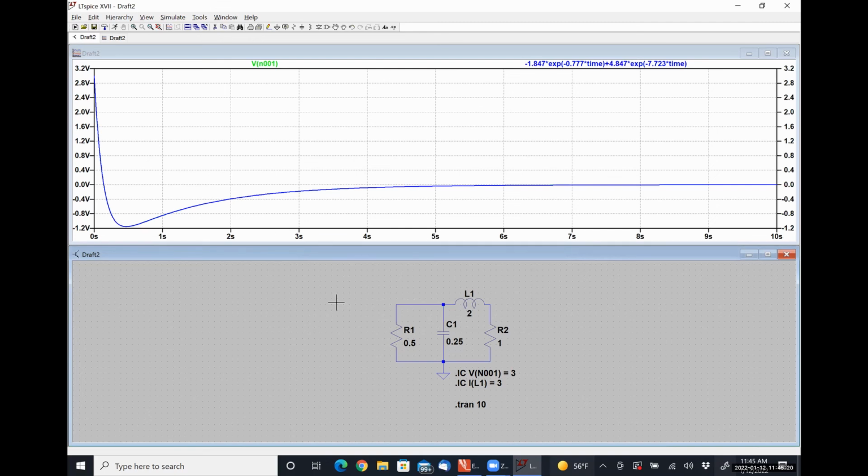And the two graphs overlap and the scales are identical on the left-hand side and the right-hand side, which means our analysis was correct. So all that differential equation work we did at the beginning, we must have done it correctly because that allowed us to calculate alpha and omega naught, which in turn allowed us to calculate S1 and S2. And then the results of our more straightforward analysis were pretty easy. And so we can tell we did everything right. Huzzah.